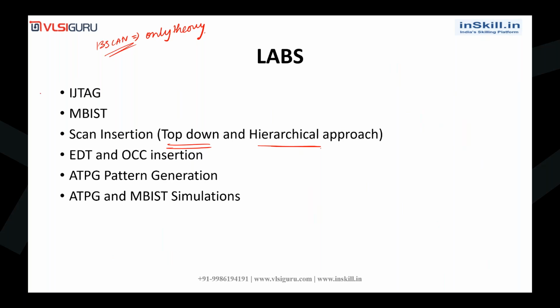As of now, in our course, we will be covering only JTAG and scan insertion. For scan insertion there will be two approaches: one is the top-down and the other is the hierarchical scan. Yes, we'll be covering both. And then EDT OCC insertion, ATPG pattern generation, ATPG and MBIST simulations. All these things we'll be covering in our labs.